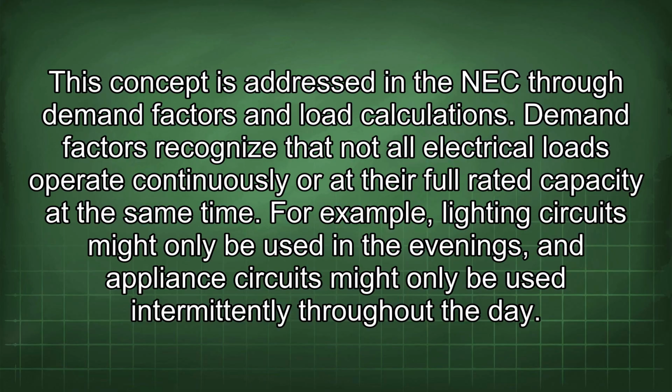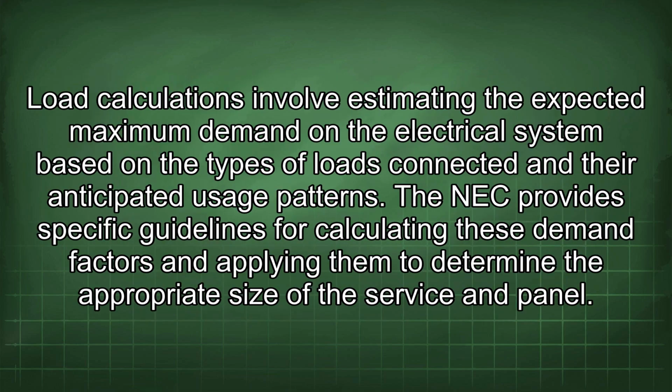Demand factors recognize that not all electrical loads operate continuously or at their full rated capacity at the same time. For example, lighting circuits might only be used in the evenings, and appliance circuits might only be used intermittently throughout the day. Load calculations involve estimating the expected maximum demand on the electrical system based on the types of loads connected and their anticipated usage pattern.